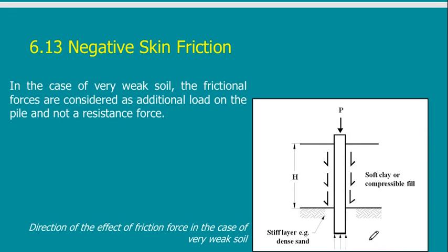Last thing is the negative skin friction. This is for your own info. If I have a clay layer, it may consolidate with time. Suppose this is my clay layer that was carrying the pile. Maybe with time it will consolidate, and once it consolidates, it moves down. It was adhering to the pile to carry it, but what will happen is the opposite. The soil will go down and it is adhered to the pile, so it will carry the pile below. So instead of carrying the pile, it is being carried by the pile.